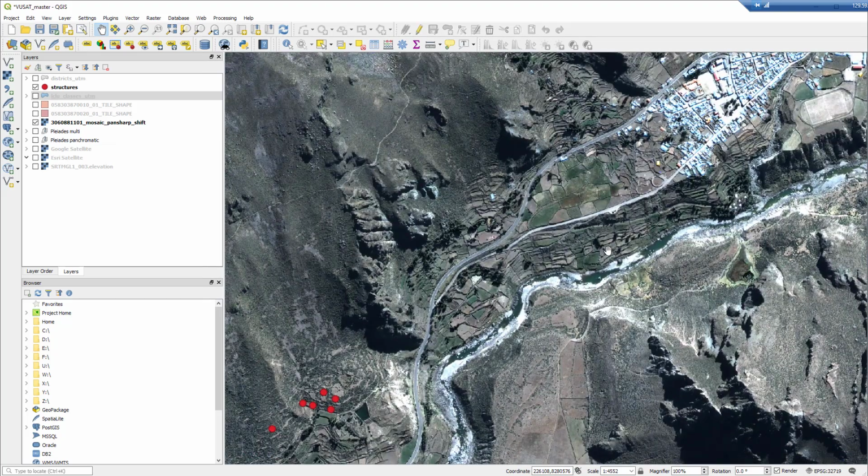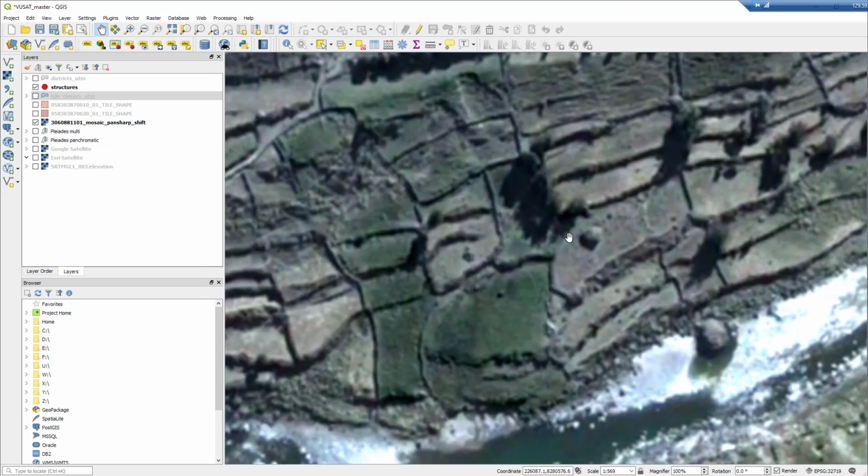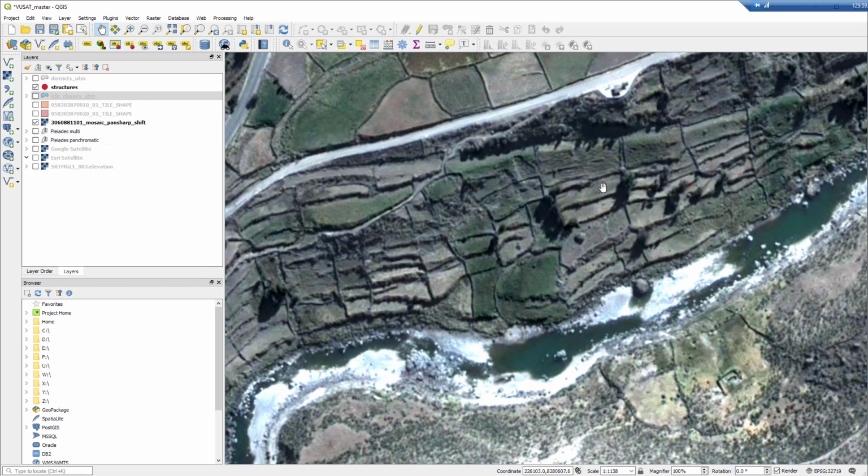Okay, so the first and the most common are bench terraces like these here, which are narrow terraces with narrow surfaces, top surfaces, and pretty high terrace walls, and they're on steep slopes, right? So what they're doing there again is they're cutting into the slope for a foundation for the wall, then they're infilling behind it to create a stable planting surface and hydrological surface.